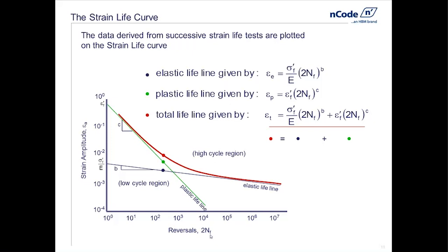What the strain life curve shows us is much like what the stress life curve shows us. As the size of the cycle increases, the life decreases. But it's interesting to look, there's a knee in the curve. There's a bend here. This is high cycle fatigue, and this is low cycle fatigue. So this is essentially the stress life curve converted into strain space with elastic modulus. And you can see then, as the strains get larger, as they are wont to do after plasticity, right?